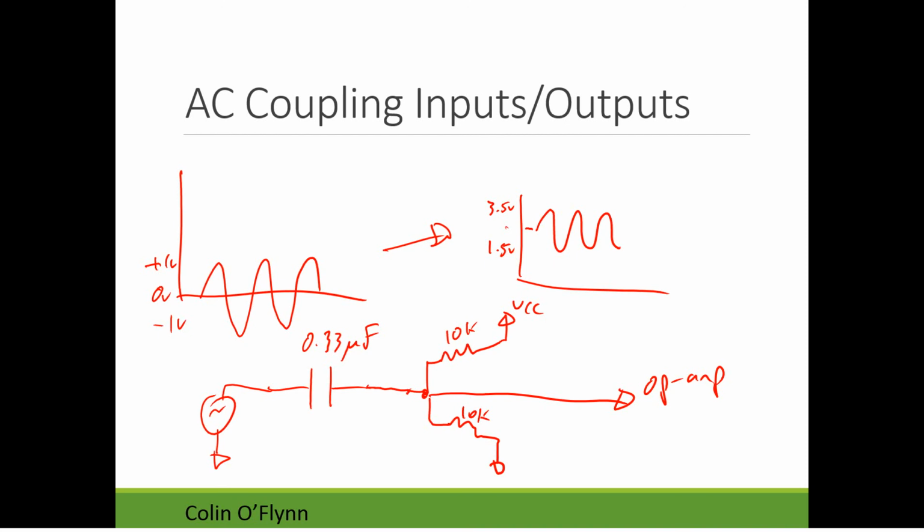The capacitor is doing what's known as AC coupling, which is to say it's removing the DC component. It's removing that 0 volts or 10 volts, whatever the normal value of it is, and it lets you choose a new midpoint here. So this AC coupling you can even use between op amp stages, for example, if you need to shift things around. It would be useful too between the sensor and your op amp, or your op amp output and the AVR input.